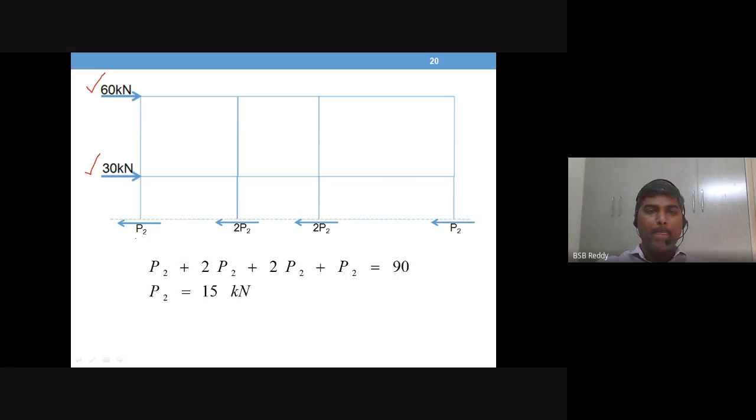Okay, so now the notation you see is P2. Reason: it is the second story from the bottom, 1 to 3. So interior columns again are 2 times P2. This is from the assumption. So the assumption here is that if the exterior column shear is P2, the interior column shear will be double.